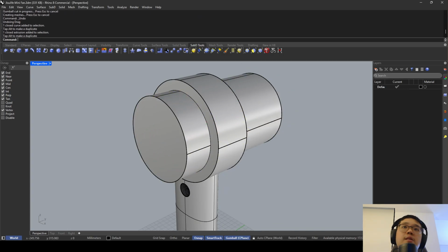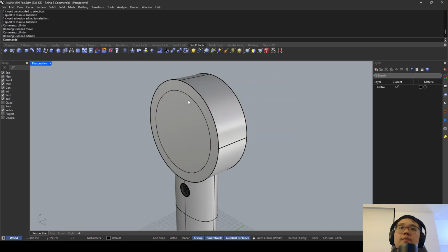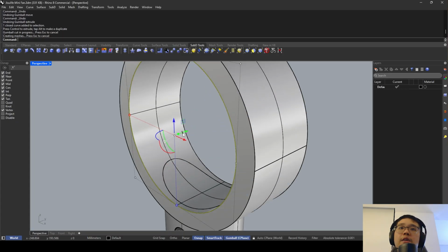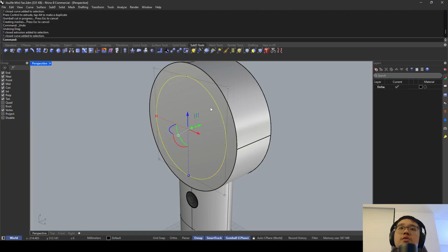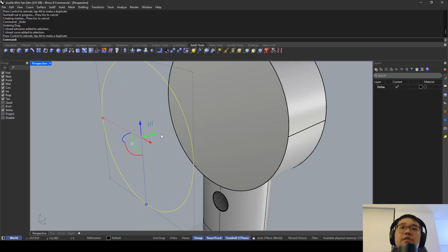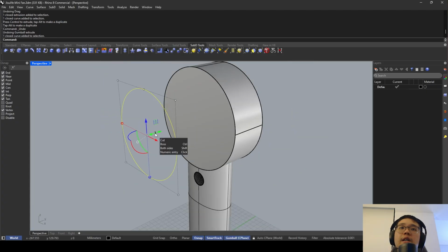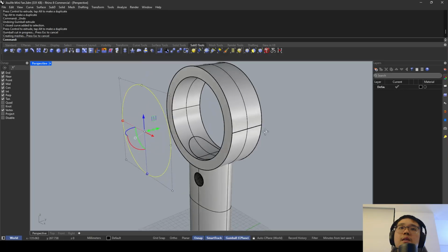That's alright. So what I did there was, if I do this, it cuts a hole like this. If I drag this line button on the gumball, so gumball, it has many features. One of them is to cut a hole directly, or I can extrude this, or I can just cut a hole like that.